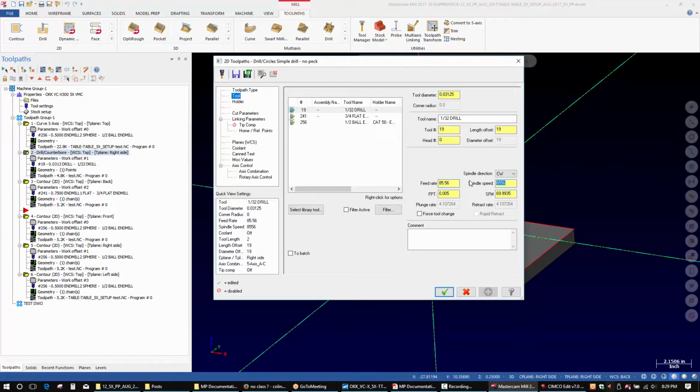It's just, how fast are you spinning the thing? Nice, 180. I've definitely gone in the hundreds, probably 100, 120 for feed rate. But a lot of times that's aluminum, so you can just slam it right through. There's a huge difference between that and tool steel.